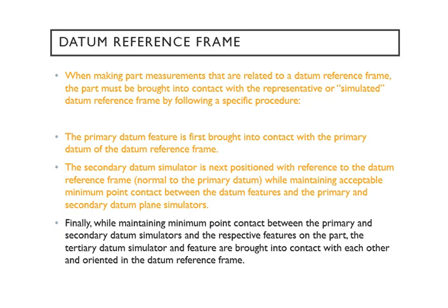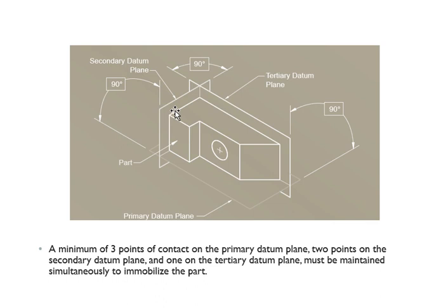So anyway, let's go, and we're doing the same thing. We go to primary and then the secondary, of course. We will get into the tertiary datum, the same thing. So we go one here, primary, secondary, and then you have your tertiary, which is this one. See, that's also normal to the primary and normal to the secondary. So they're all normal to each other, meaning they're all 90 degrees to each other. Okay, so you get the idea of the three datum planes that can be brought into connection with your part. This is all imagination right here. Yeah, it's in your mind.